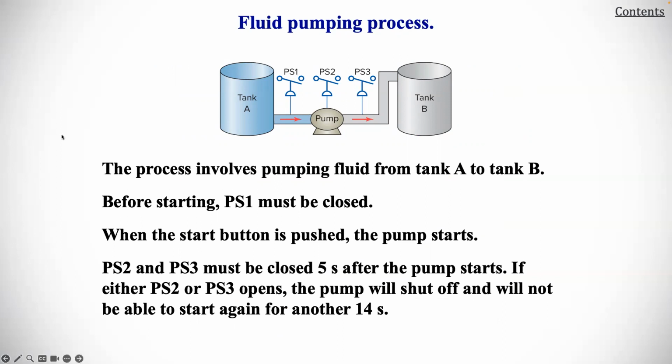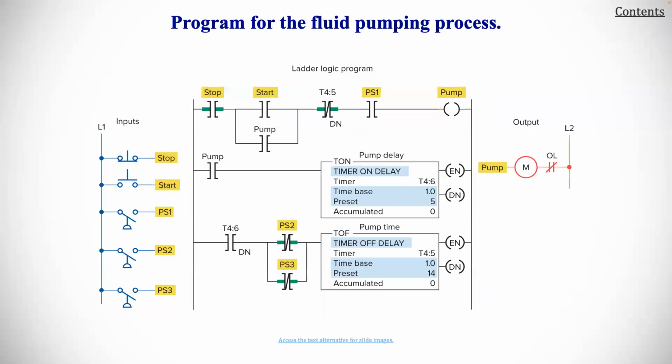tank B. Before starting, PS1 must be closed. When the start button is pushed, the pump starts. PS2 and PS3 must be closed 5 seconds after the pump starts. If either PS2 or PS3 opens, the pump will shut off and will not be able to start again for another 14 seconds. So some safeguards here.